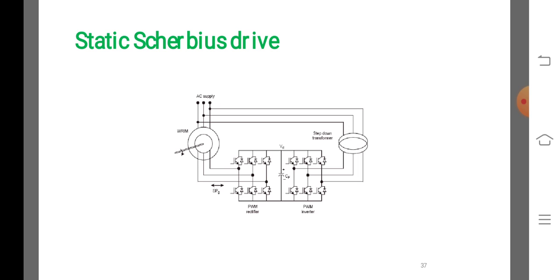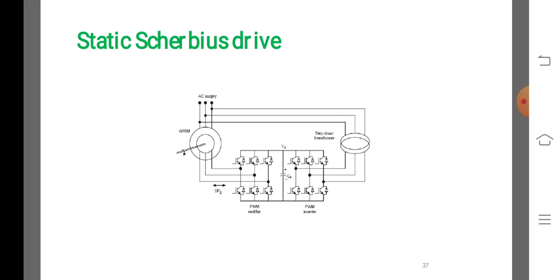Then the step down transformer at the input reduces the input voltage. A cycloconverter can operate at the best DPF for the speed range of operation. Unfortunately, like the Kramer drive, the drive also requires separate resistive starting.